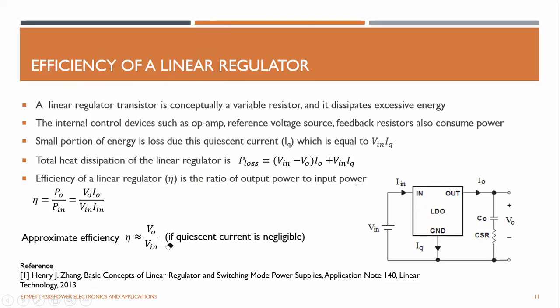In a normal linear regulator, you can't get that value because there's always a significant voltage drop across the series pass device, typically 2 volts. In that case, you can never get V out close to V in. But in low dropout regulators, this voltage drop could be as low as around 0.1 volt. That kind of small voltage drop means your output and input are almost the same. You can run your system with an efficiency greater than 90%. That can't be done in a simple arrangement.